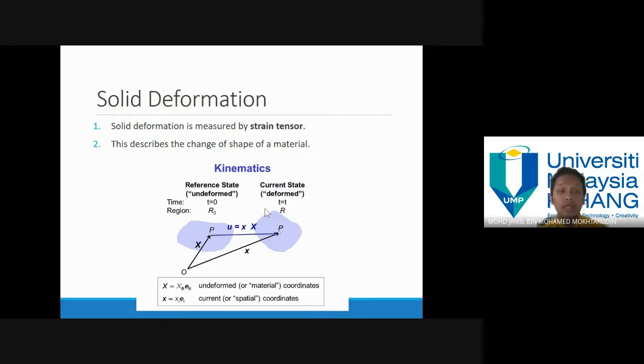But in solid mechanics, we also have strain and stress. Okay, so for strain, we also have strain in the shear direction. If you still remember finite element again, or strength of materials, you learned about shear stress or shear strain, and this shear strain and the principal stress or principal strain or normal strain can be described, all of them cumulatively, in a tensor form or in a matrix form.